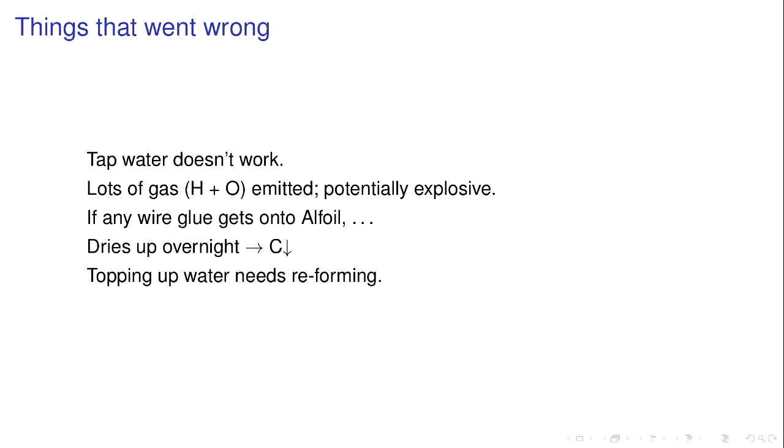Lots of gas gets emitted while you're doing this, so you need to do it in a well-ventilated area, because you're essentially electrolyzing the water while you're forming the capacitor. That's one of the reasons, by the way, that if you put an electrolytic capacitor in reverse, it eventually goes bang, because you're electrolyzing the liquid inside the capacitor and generating hydrogen and oxygen, so don't do that.